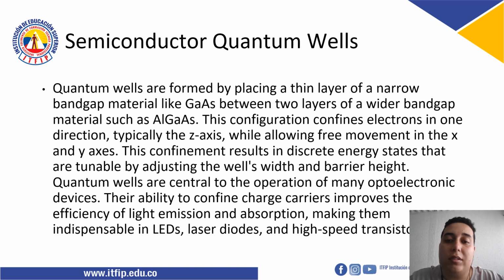This confinement results in discrete energy states that are tunable by adjusting the well's width and barrier height. Quantum wells are central to the operation of many optoelectronic devices. Their ability to confine charged carriers improves the efficiency of light emission and absorption, making them indispensable in LEDs, laser diodes, and high-speed transistors.